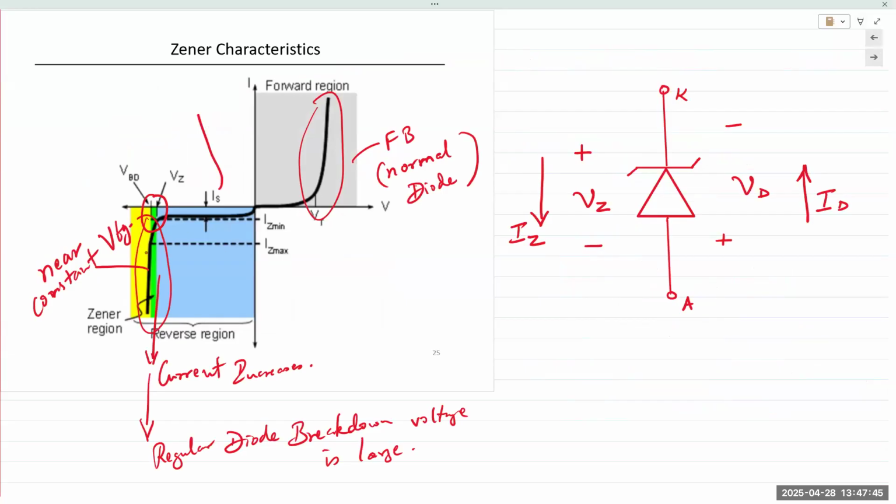Even the slight curve that is shown here is exaggerated. Once it turns on in real life, we perform these experiments in the lab for other classes. And with the 5.7 volt Zener, there's barely any movement, hardly like millivolts change. So the current increases by a large amount, but the Zener diode voltage remains near constant.